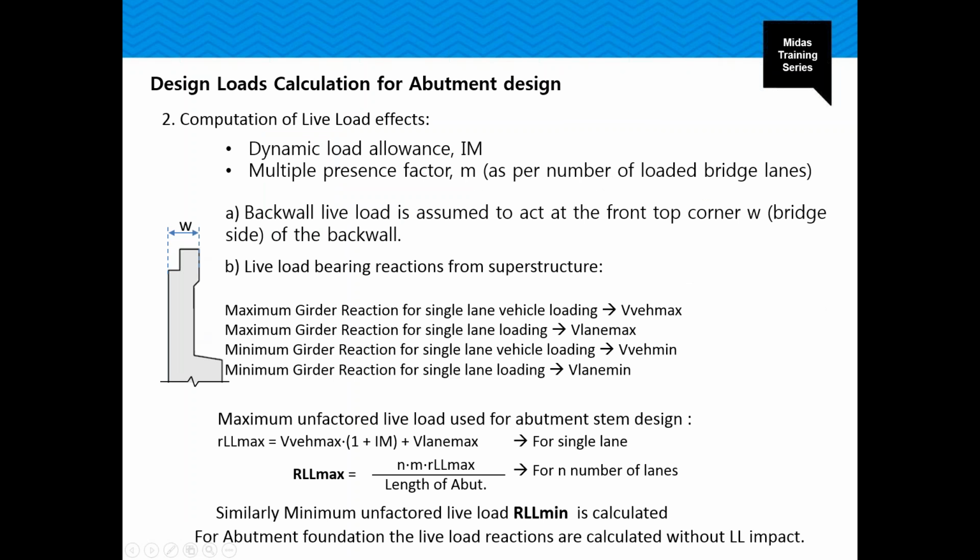And then we calculate the live load effects. So wherein dynamic load allowance and multiple presence factor, which is dependent on the number of loaded lanes of the bridge, are taken into consideration.